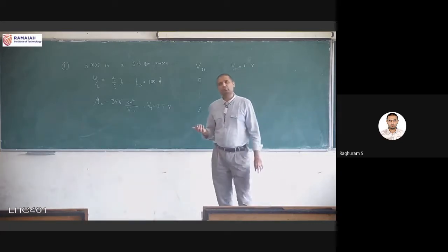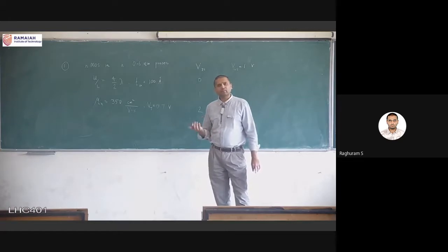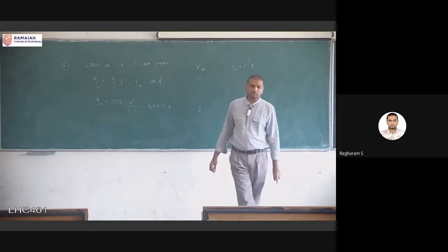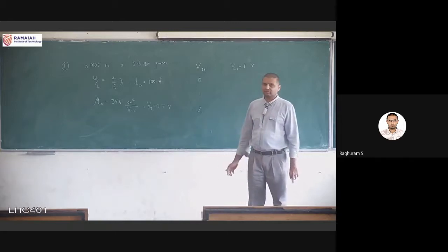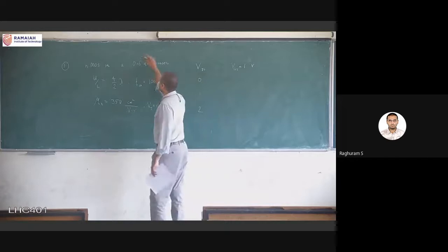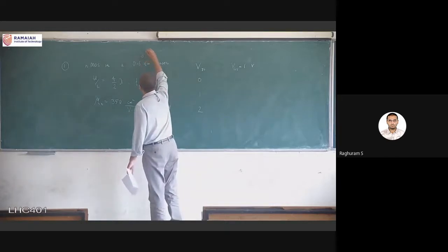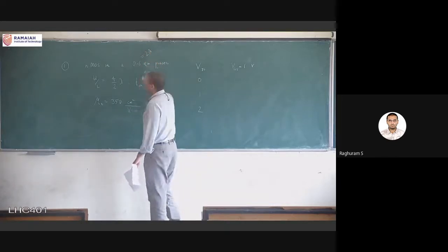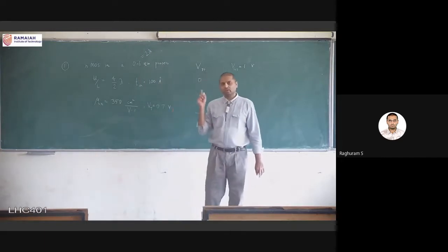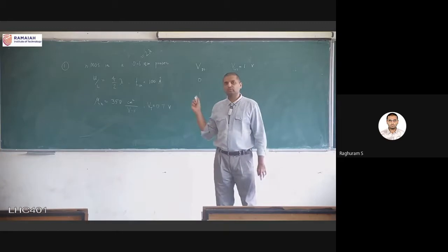Sometimes, not too many problems, there might be some numerical where we will use that number, but otherwise the actual number, that is the technology node or the channel length, directly we will not use. And another question that many of you asked, in terms of our layout design rules also, that number is 2 lambda, that is 0.6 micrometer is equal to 2 lambda.